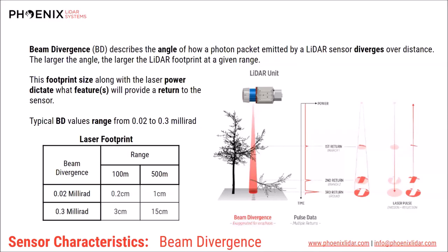Similarly, with a wide beam divergence over a forested area, you're able to capture much of the vegetation, but you might minimize the ground returns through this. So it is a balance, just as the balance of pulse repetition rate and beam divergence dictate what sort of features and how clearly they are captured. The features that you're capturing also play a factor. So we're going to be layering this cake with many different characteristics that all play hand in hand, but are all very important to understand.